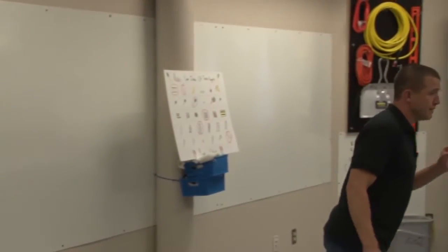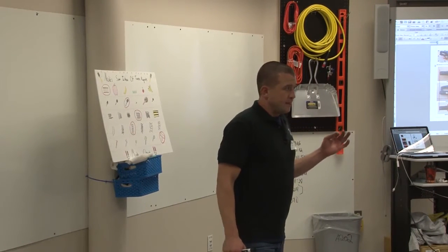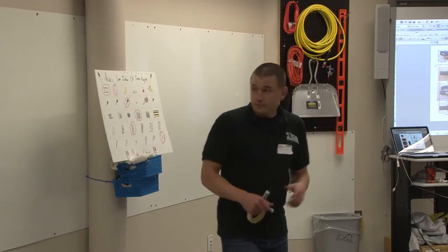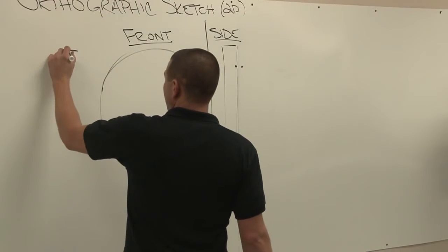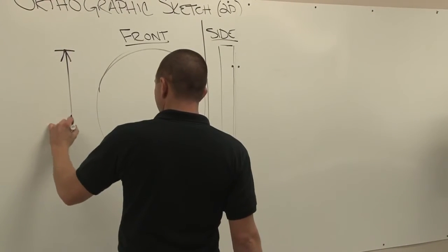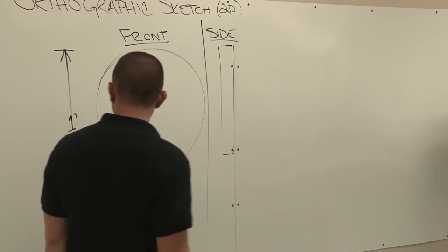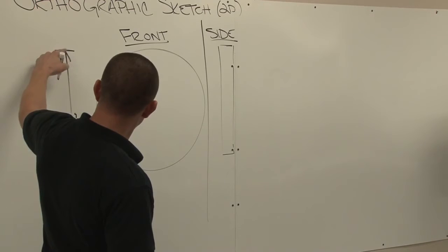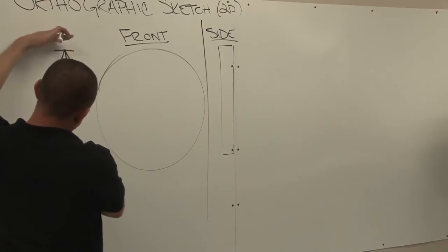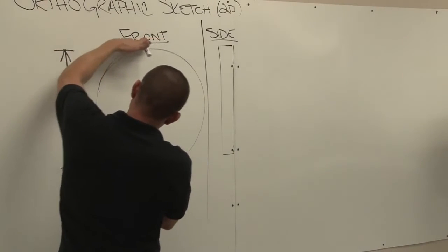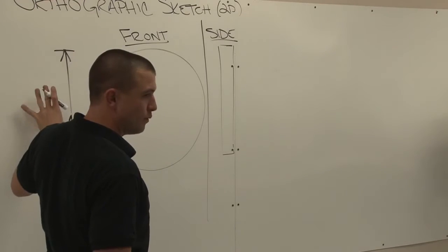But the way we draw those dimensions is very different than maybe how you do it in a math class. If that penny was 1 inch across, you would have to label the penny as 1 inch outside of the penny with this special line that has arrowheads on each end at the top and bottom. It tees off with arrowheads. You split it in the middle, put the dimension, and it sits at the same height as the front view of the penny. Now everybody knows this penny is 1 inch high.